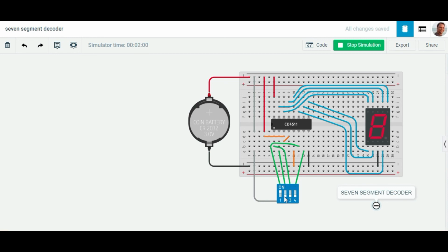If you build this circuit in a lab environment, it will give you the same output with the same connections. Now the last thing, as I said earlier: if you want to check whether all the segments of your 7 segment display are glowing properly, we just connect the circuit and provide 8 as input.